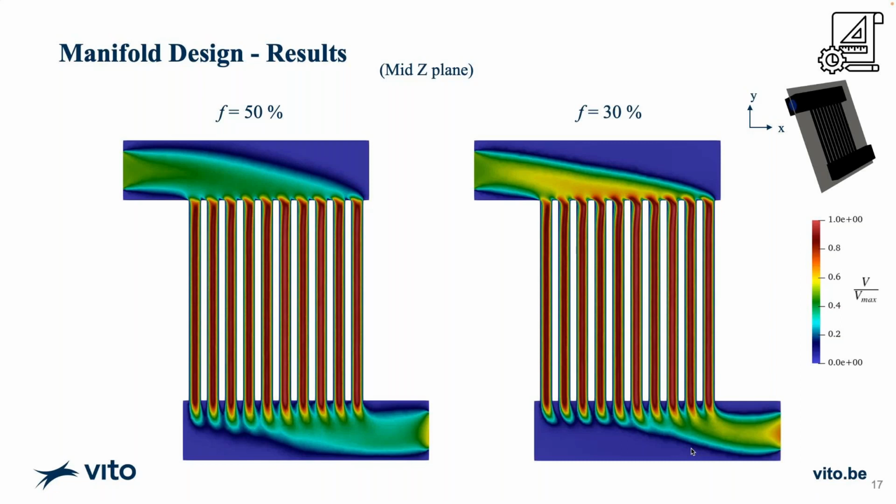Yeah, so for that Q interpolation, you always have to start with a lower Q because essentially, irrespective of the flow regime you are in, if you start from a very high Q value, your problem is very stiff. That means any change that the optimizer tries to make in the material, the fluid just cannot flow there. And then it will quickly go to a local optimum that does not probably make sense and can be highly governed by your constraints, for example. So the approach that we typically follow is that you start from a very low Q and then you constantly observe your optimizer history, and as soon as you see it start to converge, you pump up the Q again and then you continue the process.